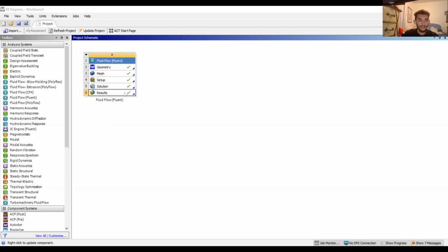Then for our pressure contours, we hit that button again, name it pressure contour, so again, location symmetry 1, but the difference now is our pressure is what we're looking for. We kept our contours at 50, because that's sufficient. So we hit apply, and then we're going to look at that now.